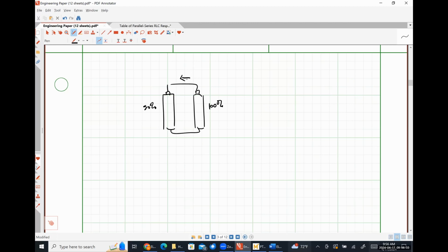And so people would just not pay attention, throw it in their bag, and then open up their bag a couple of hours later and just find a big melted plastic mess. And it's because the batteries just heat up so much by trying to balance the charge across all of that, that just melts the plastic and then ruins their robotic kit.